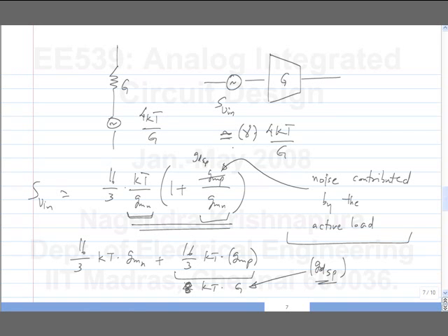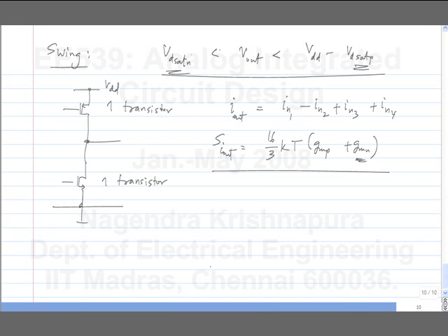Otherwise, if you are entirely in the voltage domain and operating from a voltage source supply, the best deal to get the best signal to noise ratio is to lower all the impedances. All our batteries are voltage sources. If we had current source batteries, then you would do the other thing. You would make everything high impedance. So for every one of our cases, because we have voltage sources, we should lower the impedance to get high signal to noise ratio. Or if you try to minimize noise in this case, you will get a low signal swing.